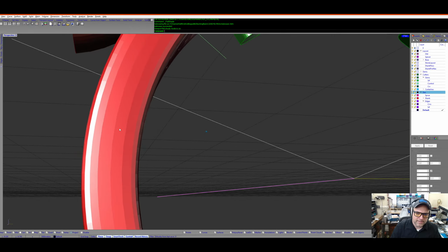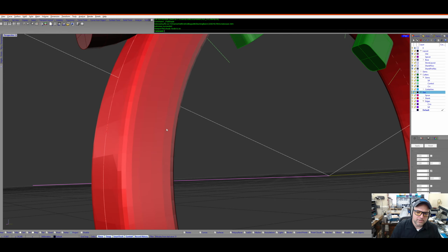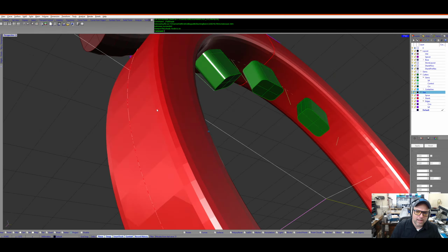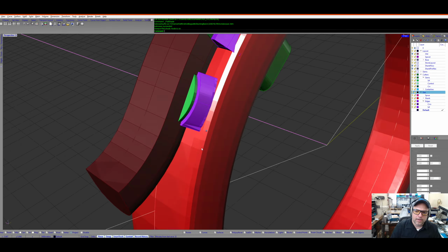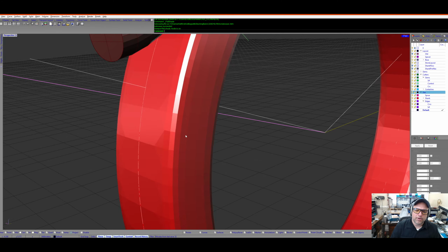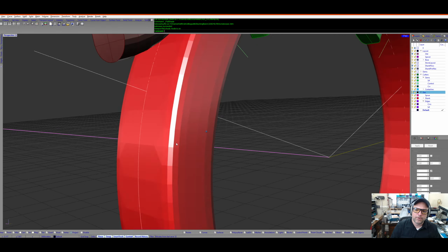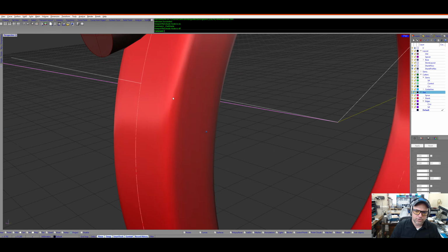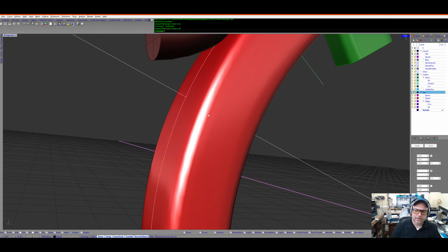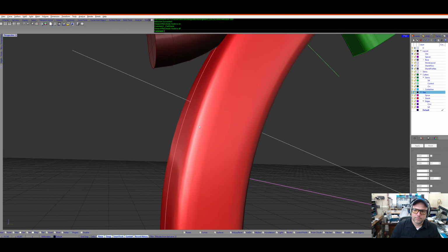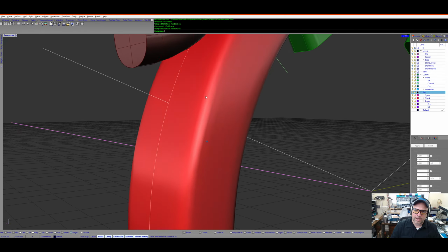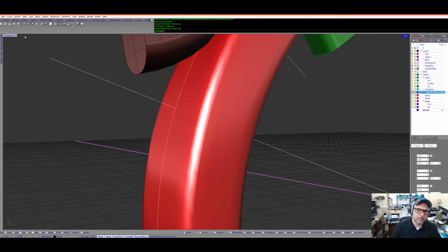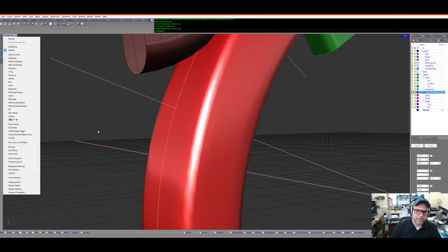Okay, you can really see, now this is a render mesh that's low quality, but you can really see how many triangles Rhino's working with, because a graphics card can't render NURBS. It can only render meshes. So this is what's being sent to the graphics card to render, and you can change that and say smooth shaded, and now the graphics card's saying, all right, very few quads to this mesh, and just make them look more smooth than they are. So this is kind of like the actual thing.